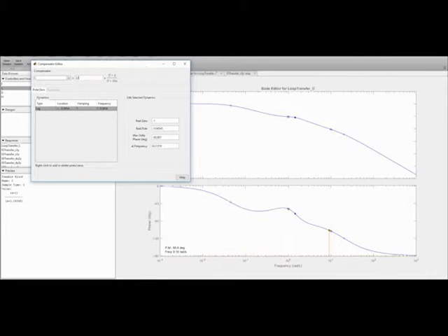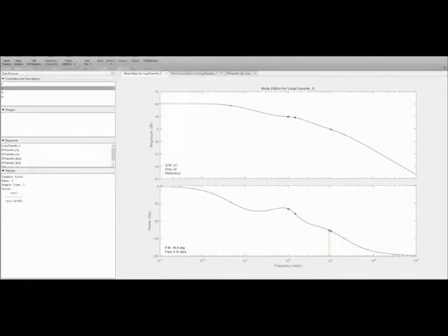So it's maybe a little bit tough to see all that moving around dynamically, but you can see the pole I added from the lag controller and the zero I added from the lag controller, those are given in red, not blue. And so the dynamics of what I added is pretty much only in the low frequency region, and I haven't affected the high frequency region at all. Basically, low frequency is the steady state response, high frequency is the transient response. So everything I'm doing, I'm only affecting low frequency.